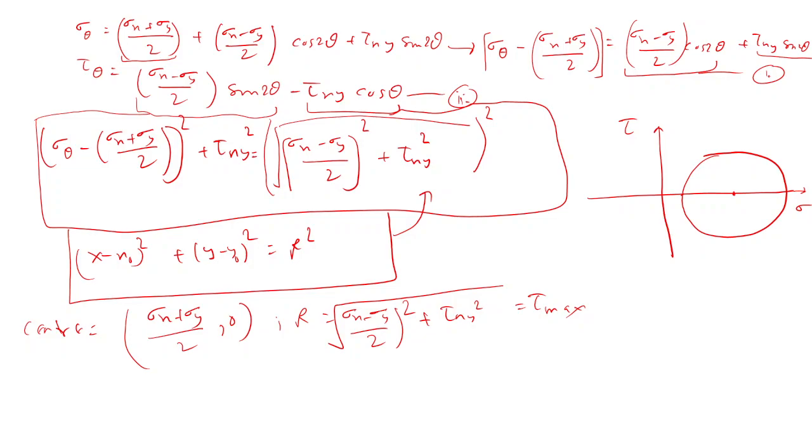So I will ask you quickly. You tell me how the Mohr circle will be made if sigma 1, sigma 2 are both positive. How will it be done now? The circle has its center on the right hand side and the whole portion on the right hand side. This way, right?